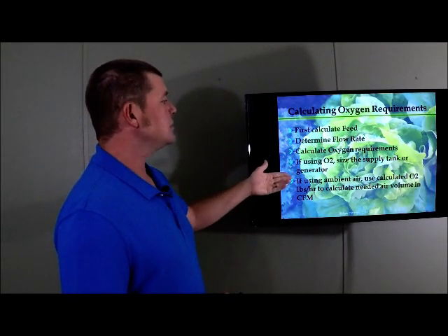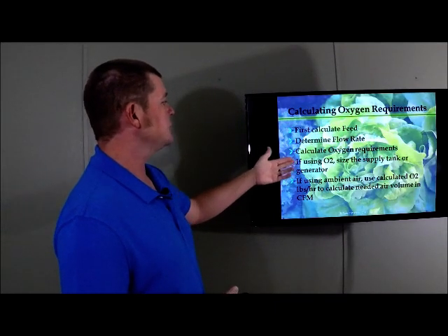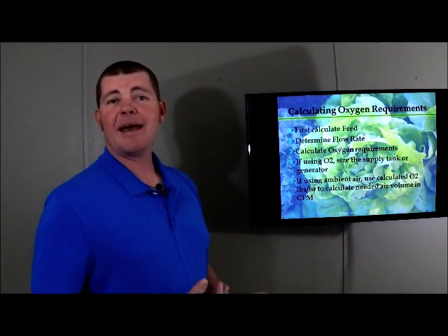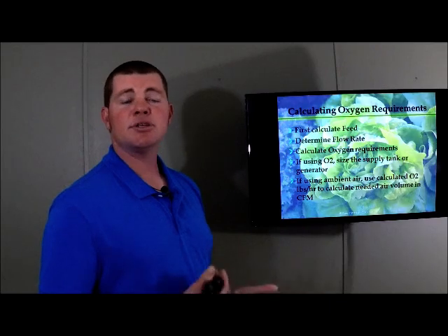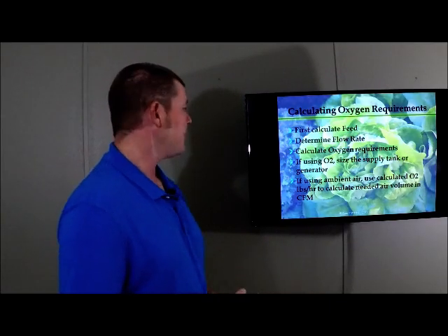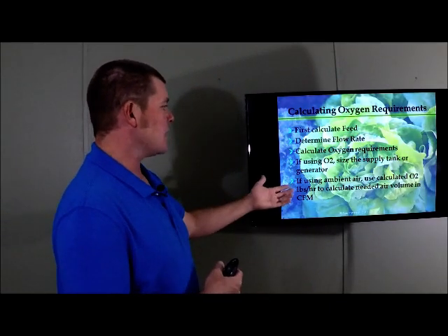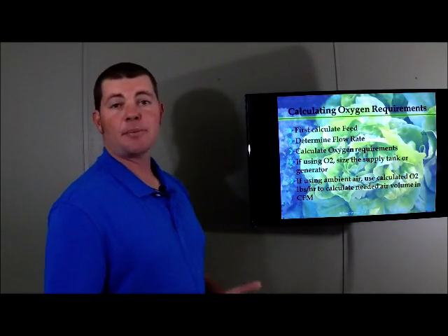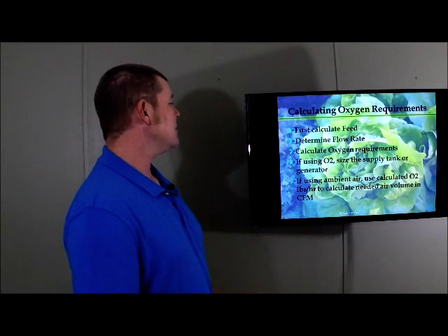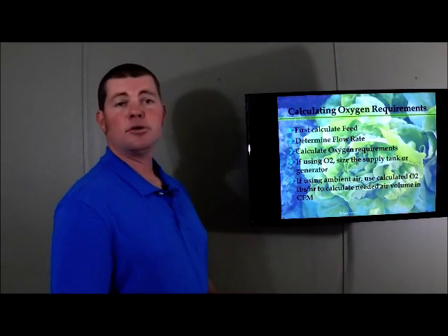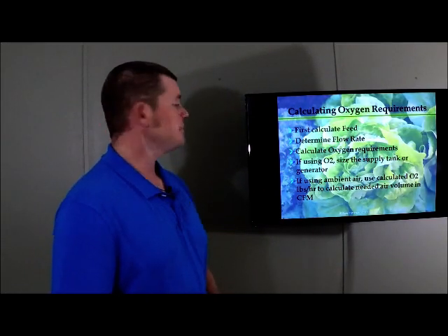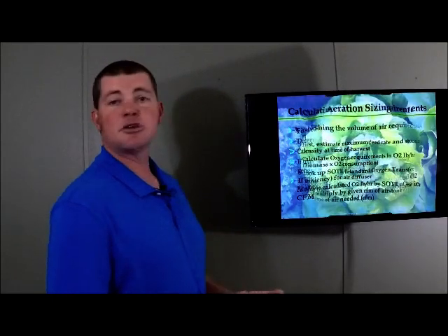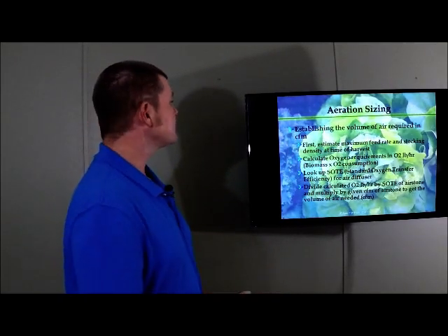If using oxygen, we size the supply tank or generator using how many pounds of oxygen we need per day, using that calculated number. If we're using ambient air, we can also use the calculated oxygen pounds per day or per hour to calculate the needed air volume in cubic feet per minute, or liters per minute for our metrics.